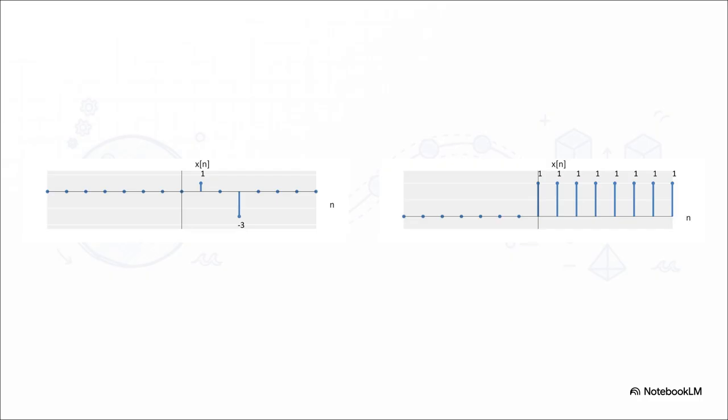On the left, that's your input signal, your clap. We call it x[n]. And on the right, that's the system's own unique personality, its impulse response. We call that h[n]. Think of that one as the shape of the canyon. It's how the system reacts to just a single sharp input.